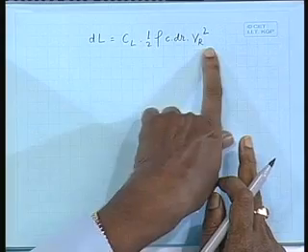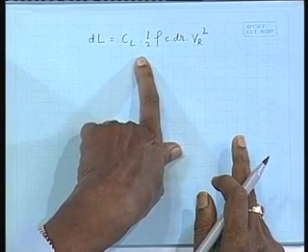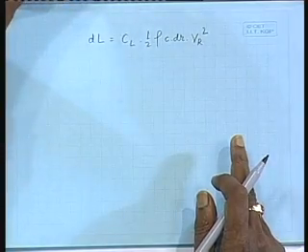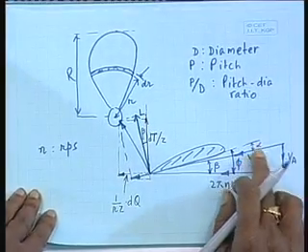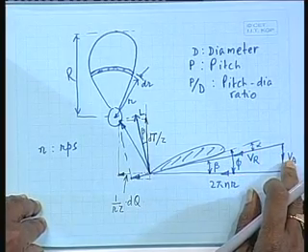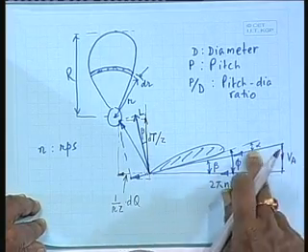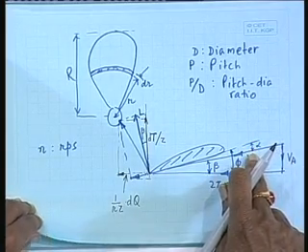If we get the lift coefficient by some means for a section of that shape as a function of angle of attack, then I can calculate this CL, knowing the angle of attack, isn't it? Can you note that in this diagram it is very easy for me to calculate the angle of attack? If I know the VA, I know the tangential velocity. So, if I draw this geometrically, I can find out what is the angle of attack.